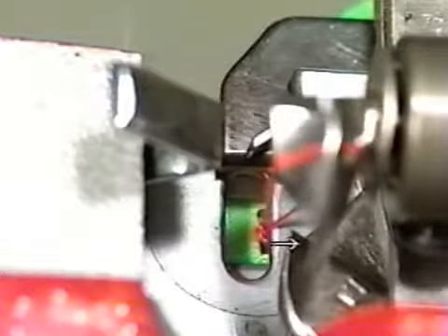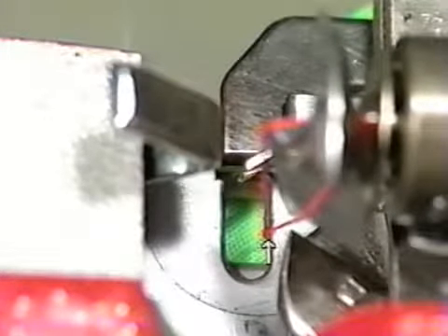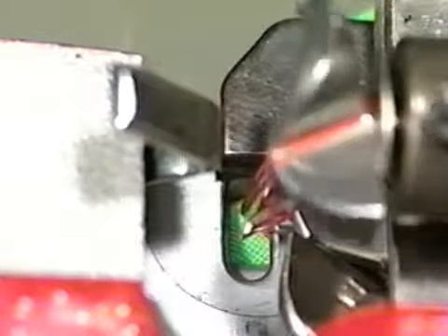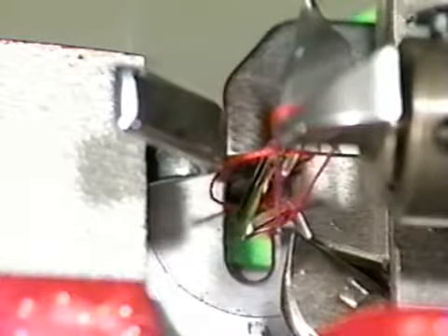When sewing a 4-hole button, the button moves in the direction of the arrow at the 9th stitch. As a result, the thread triangle shifts from its correct position. In this state, the looper point cannot pass the center of the thread triangle smoothly. At this time, adjust the longitudinal position of the yoke slide using the yoke slide cam to allow the looper point to pass through the thread triangle.